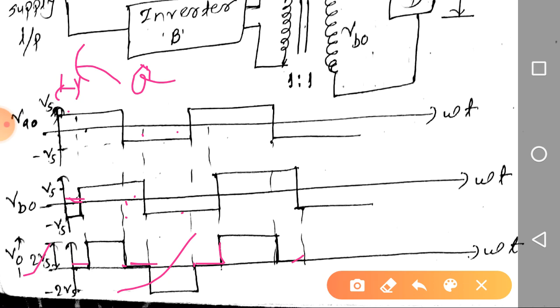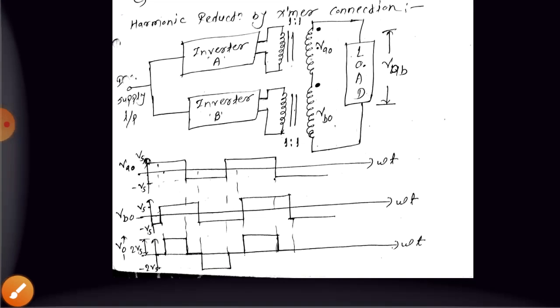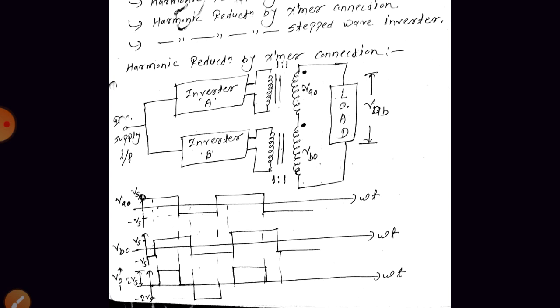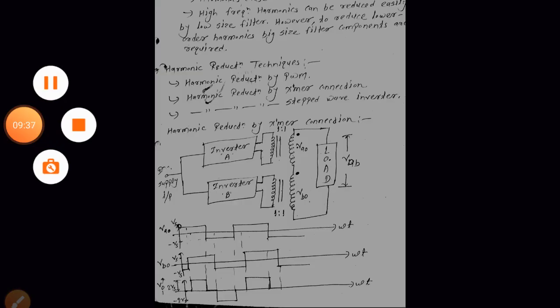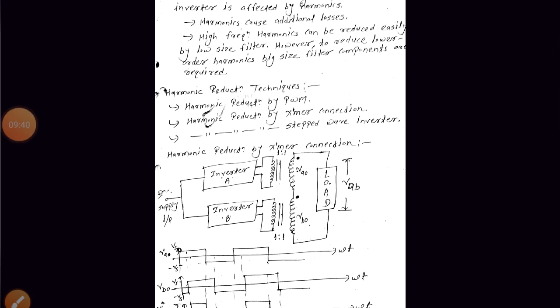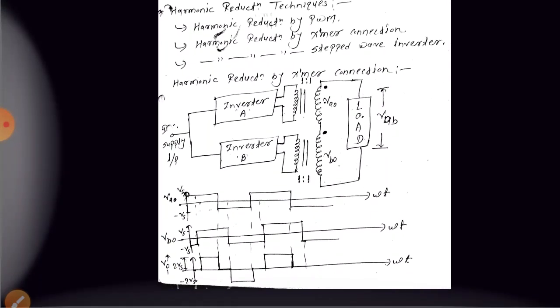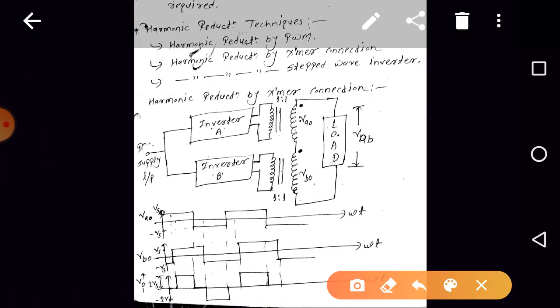And as we know, the quasi-square wave will definitely contain fewer harmonics compared to the square wave, because we have already discussed in single pulse width modulation that the output voltage is a quasi-square wave. Are you getting the point? We can remove the harmonics. Similarly, by keeping how much phase displacement, which harmonic can be removed, we are going to discuss in this same method only.